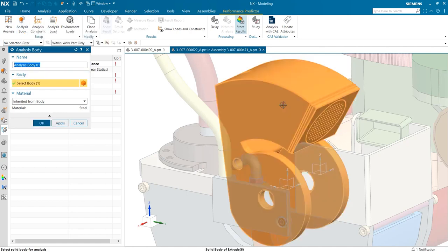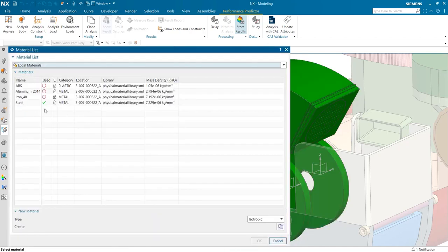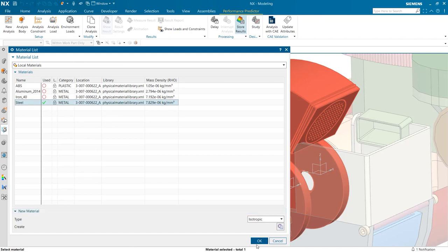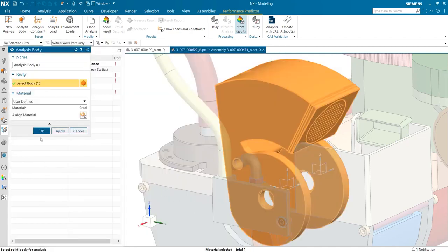It is important to notice that this is where we can choose the material of the part. You can either select a material of your choice or opt to use the material that has already been defined in your assembly previously. This is an excellent way to explore the impacts of altering your material makeup and see the effect it has on the product's structural integrity.